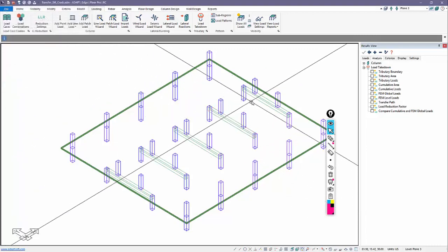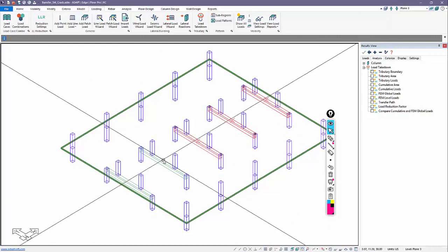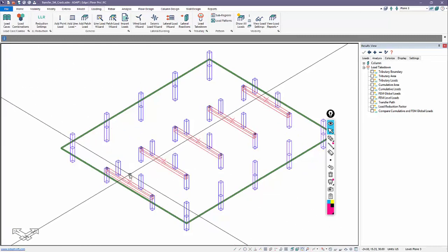Okay, now I'm going to select these beams. And in this case, we don't know to what extent the beams have actually cracked. We're just applying a modifier that is approximate. Maybe the ACI code or another code says for second order effects, for strength, for this, for that, we apply certain modifiers.